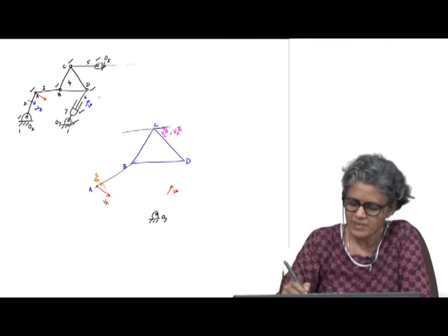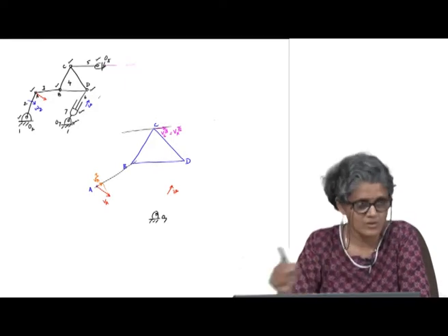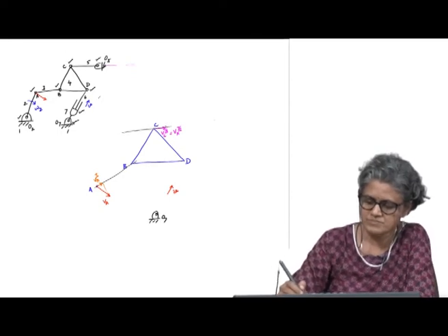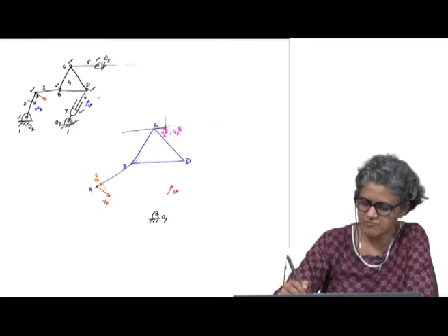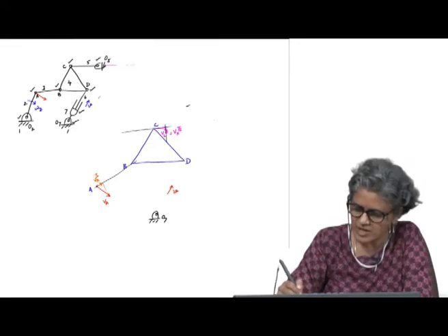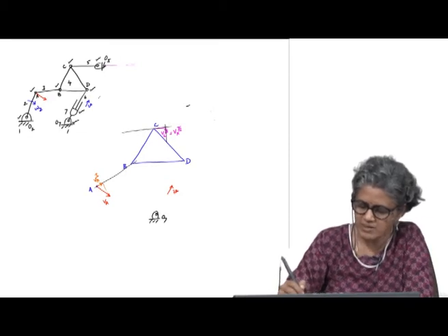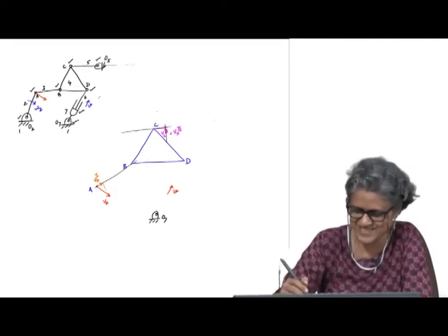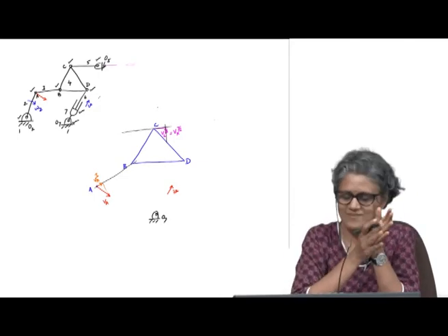The other thing is, I know that the absolute velocity has to be perpendicular to O5C. So this would actually be very short. If this is the other component, perpendicular to this, so the other velocity is this, and the sum of these two components should be perpendicular to O5C. So these two will not meet, that is the problem here. Essentially these two perpendiculars have to meet, because of my choice of the x.